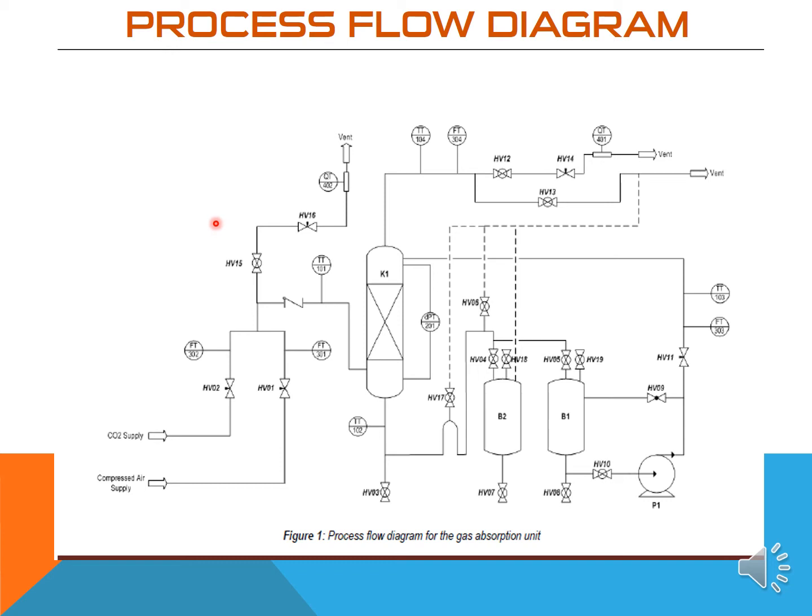First, perform the general startup procedure as I have described before. Open valve 12, valve 13, valve 14, valve 15 and valve 16.